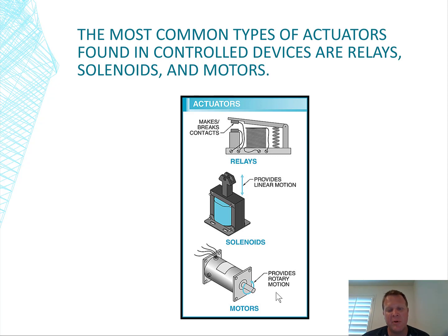The controller is saying, I sense the information, and by the logic that was given to me by the programmer, I am now asking the equipment to do this, and it's sending out information through low voltage to deliver some cooling, turn the refrigerant on, regulate the airflow, or turn an electric heating element on.